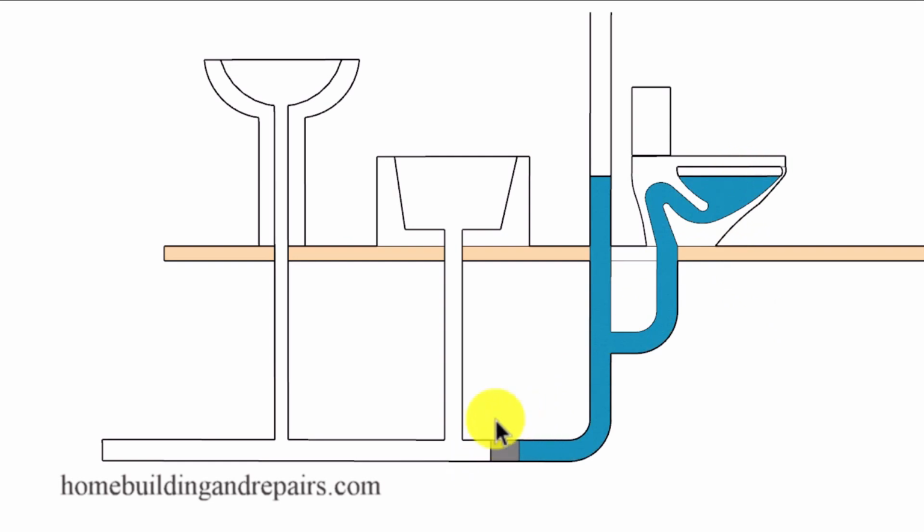We have a clog in our drain pipe, and the water would be backing up into the toilet. However, we'd be able to use our bathtub and our sink without any problem. The clog is behind these pipes here. So with the clog located right here, all of these drain pipes would be open and allowed to flow to the sewer or our septic tank.